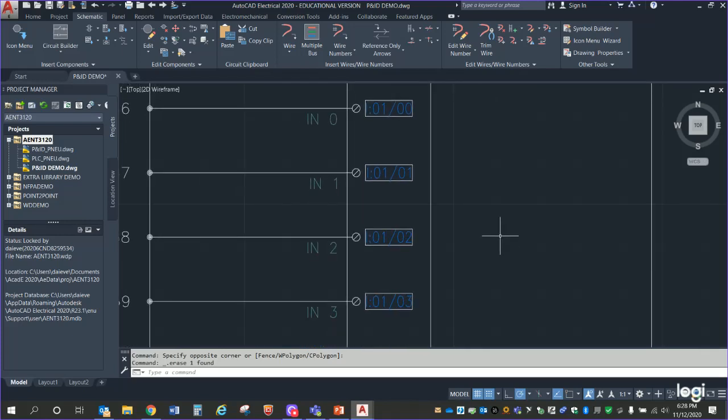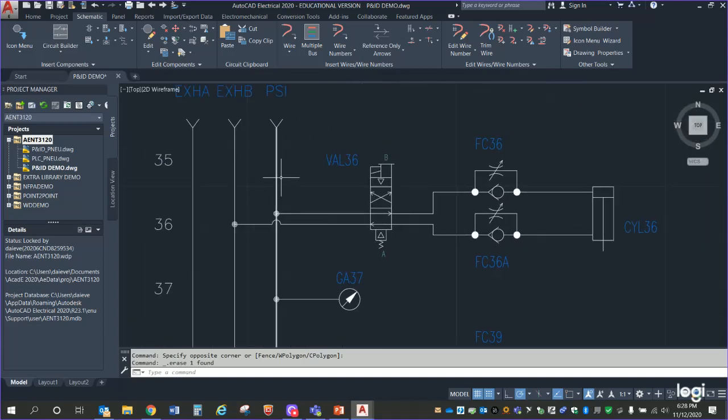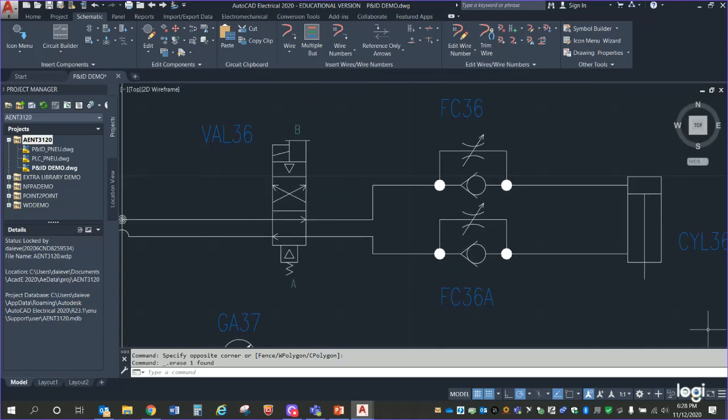Okay? Now when a cylinder extends out, as an example, if a cylinder is going to extend out and clamp something in, so let's say one of these robots is going to weld something, and one robot places a part inside of a fixture, and then the pneumatic cylinder is going to come down and clamp it into position. What's really important to know before that robot starts welding? That it's fixtured properly, and that cylinder's holding it in position. That's really important to know. Just because I turned this valve on doesn't mean that that cylinder extended.